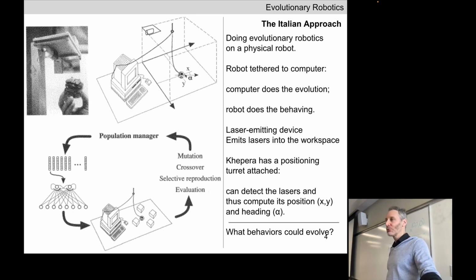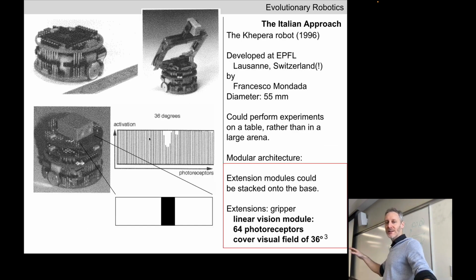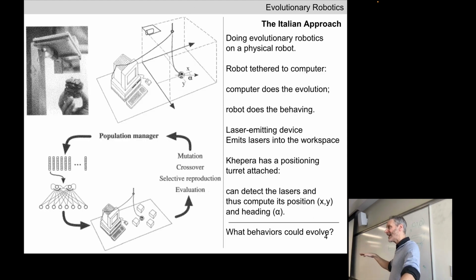The only thing the robot does is receive numbers along these tethers that cause the wheels to turn. And the robot is then going to send back along the tether the results of the sensor values. Yeah? So the robot is going to sense and act, but the computer is going to think. Make sense? Obviously, 90s technology, not possible to run a lot of things on this little tiny mobile machine. We want to do as much as possible on the computer.